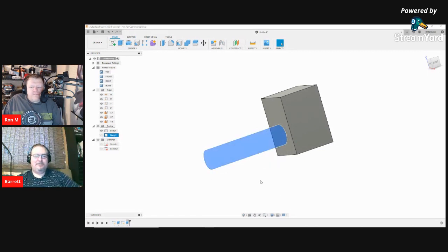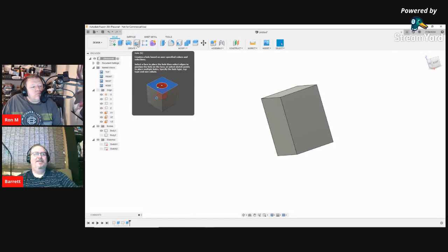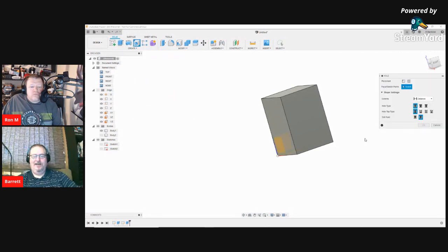All right. So now we're going to go up to the top menu. You'll see a create. Under create, there's something that looks like a hole through the. You're almost there. That one. So now, if we click on the face where you want this hole to begin.